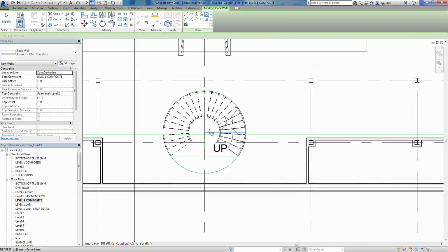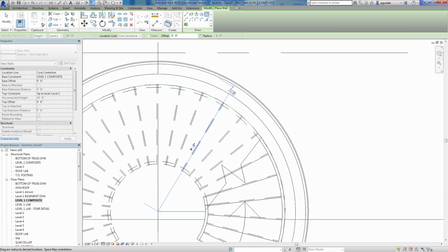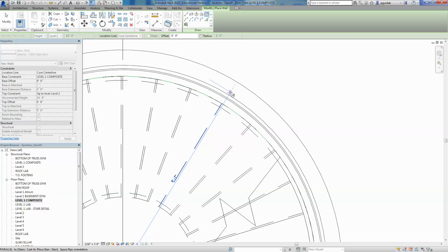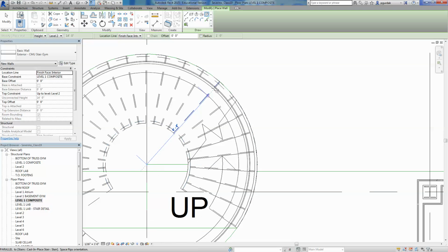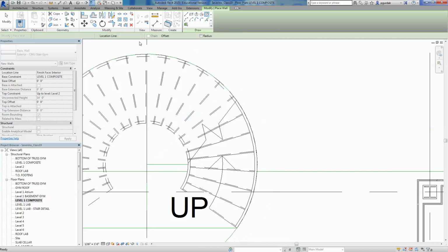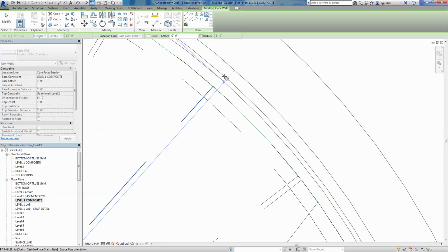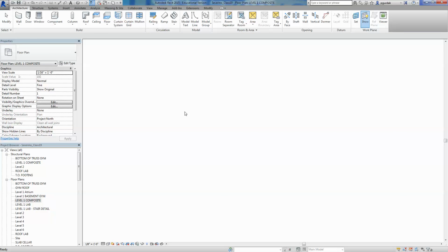We're going to do a circle wall from the center, and you see how the gypsum board is outside, so spacebar to place it inside. The clean area, actually probably, let me do it again. We should be with exterior for finished face interior, spacebar, then finished face exterior. So there's a couple of changes we have to do till we make it perfect. There we go. Let's go to the 3D to see what we have just done.